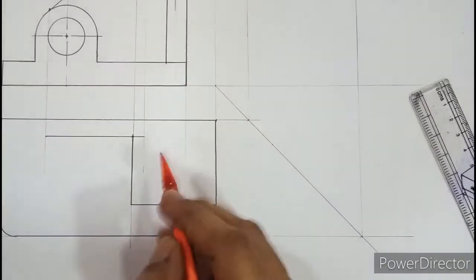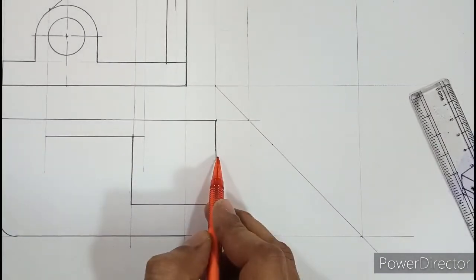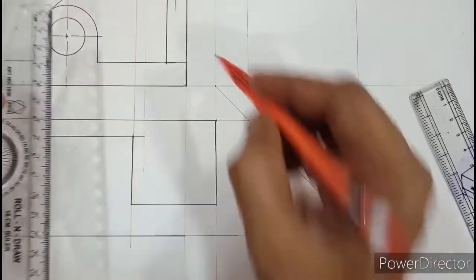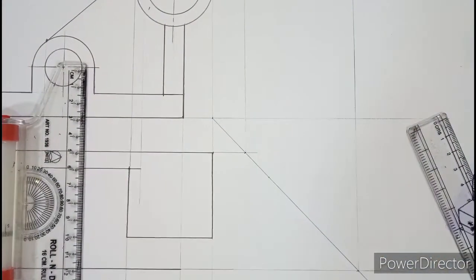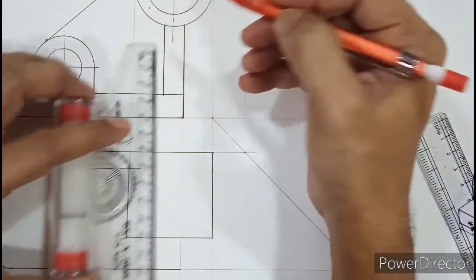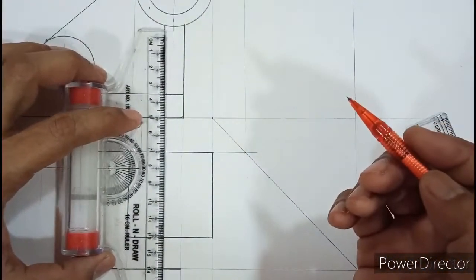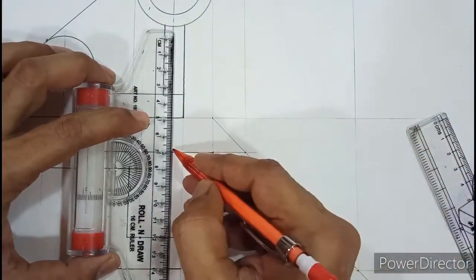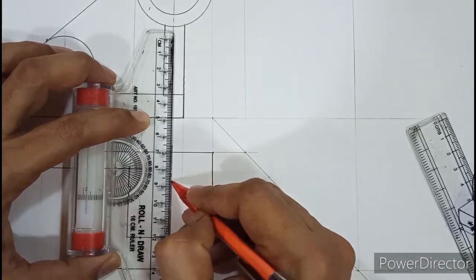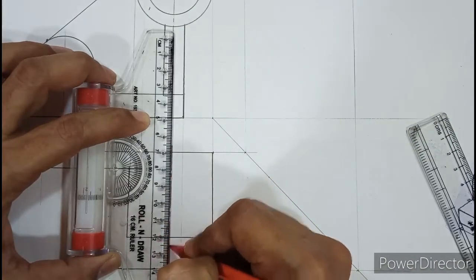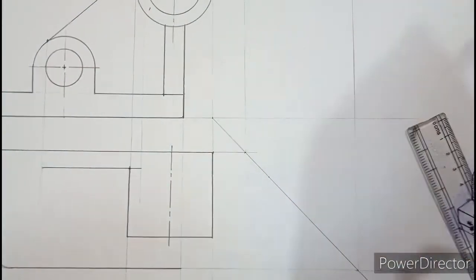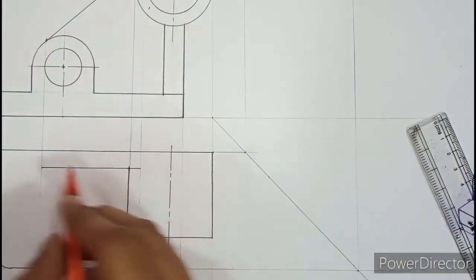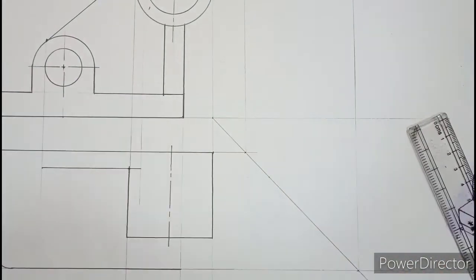Well, now as we know that whenever you show a circular surface, it has to be supported by an axis line. So the axis line is already ready in the front view. So in the front view you can see there is an axis line over here. I'll align the scale with that axis line. Okay, and let me draw big dash and small dash just in and around the cylinder. See, the cylinder ends here, so the axis line should end somewhere beyond that. Okay, so this part of the cylinder is very clear.